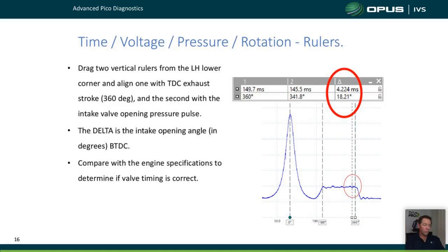And I know a few of you have done this. I do it quite a bit to try and compare and check if I've got cam chain issues, and it works. It's really, really good. I tend to do it more on the Holden HFV6s, those Holden or GM, I can't remember the prefix on it, LFA or something like that they call them, LFW engines, the ones that stretch the cam chains. And I tend to do it just to see, because we are allowed a little bit of margin there in stretch, so we don't actually have to replace the chain straight away.